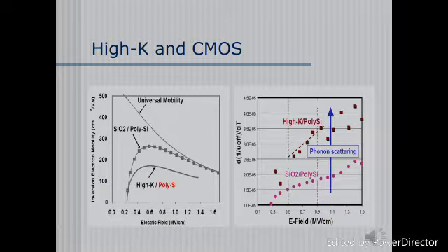This leads to the next problem: Fermi level pinning, where powering the transistor from cutoff mode to saturation mode required more voltage than theoretically required. And once the transistor was successfully turned on, the charge carrier mobility became very low, which can slow the speed of the device. The phonons slow down the passing electrons when they pass through the metal gate and severely reduce their speed, slowing the transistor. But by increasing the density of electrons in the gate electrode, the oscillations can be avoided. By using a metallic gate rather than a polysilicon gate, we can conduct more electrons than the former, up to a scale of a couple of hundred.